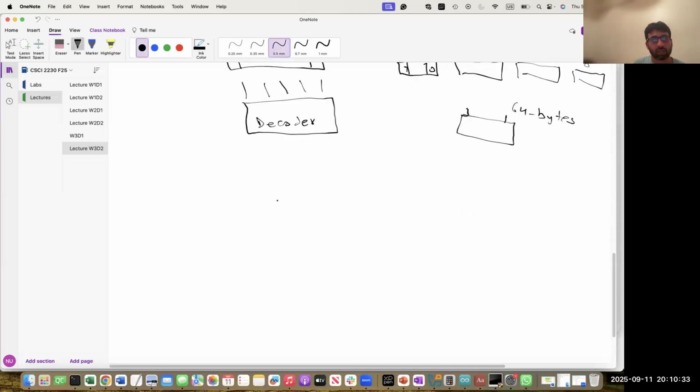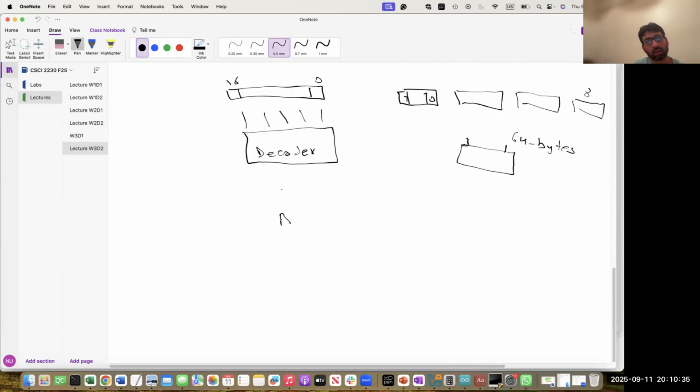So, for example, let's say you have a processor or a microcontroller which allows you to add two numbers together which are located in the memory. So, for example, you can say, okay, add 0x200 and 0x220, which basically means read the data from this memory address. A is located here, let's say, and read the second operand B, which is located in memory at this address, add them together and put the result back in this location, right?